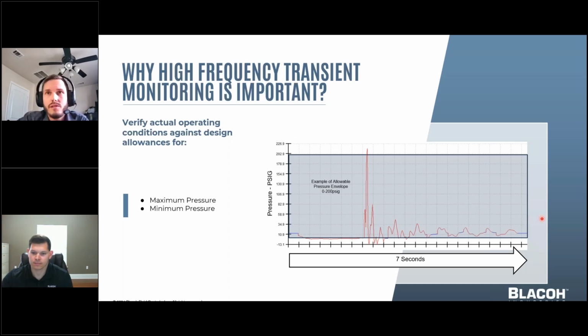Typically, this can be accomplished by closing the valve quickly for most of the travel, but closing the last bit of travel very slowly. However, many times these operational changes are not favorable or do not sufficiently mitigate the effects of Waterhammer. A precharged surge vessel can be added to the system, or usually teed into the line, to act as an immediate source of energy or as a place to accept energy as needed.